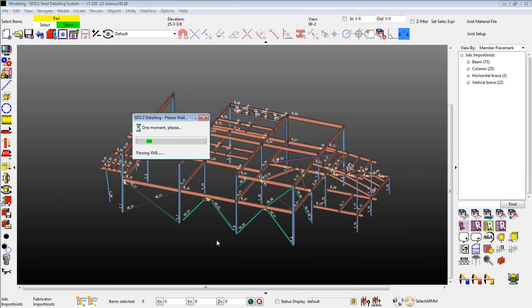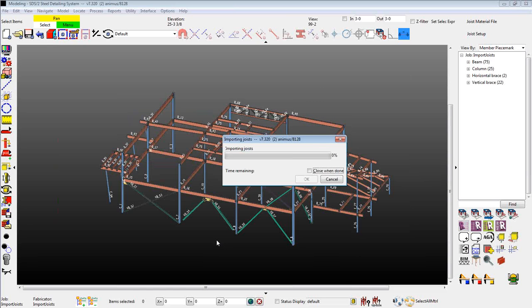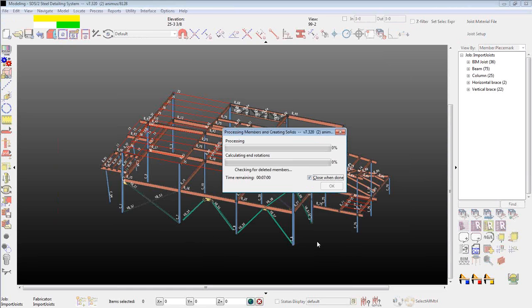So go ahead and click OK here, and this is going to actually import joists that came from Vulcraft. They export this in an XML file. In this webinar so far, to show you the pre-configured panel layout and the connections, I've always just done a regular parallel joist. When we do the import, we can see that we have some different shapes in there rather than just the parallel joist. We're going to see a pitched joist in here. We have an arced joist that can be imported as well. I guess I need to click OK to this window so it can process and create solids.